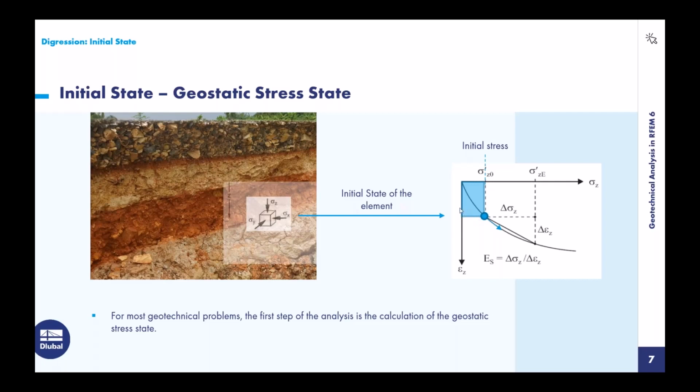What we don't need is this displacement that is calculated as well. We are not interested in the deformation that happened to the soil due to its self-weight. For us, if we look at this picture, this is the start situation, and we want to know the deformation that happens for the further loading. So what we do is we reset this displacement to 0. So we have the stress state, we have the correct stiffness, and the deformation is set to 0 so that it starts to count the deformation from our further loading from our building.